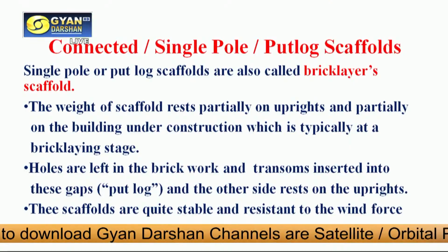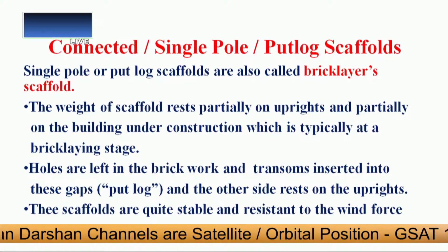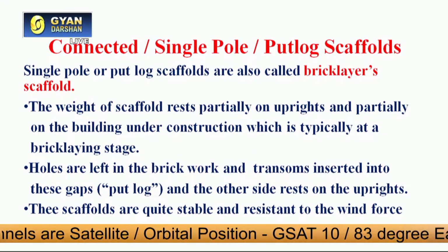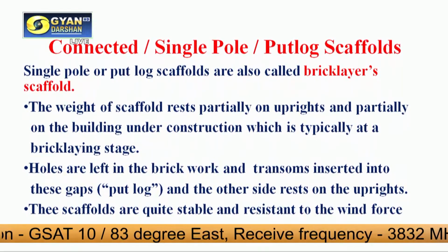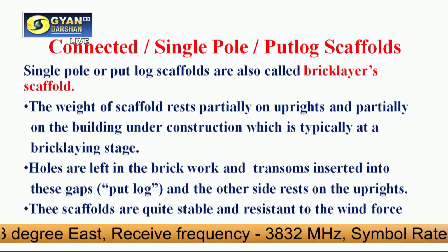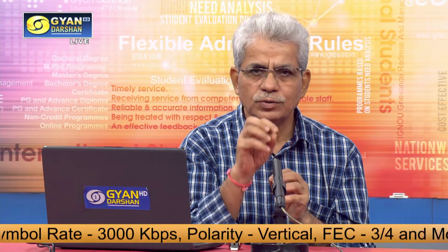The weight of this scaffold rests partially on the uprights and partially on the building under construction, which is typically at a bricklaying stage. As I told you, during the construction we are leaving some openings or holes in the wall, and in these holes the horizontal members, the putlogs, go in and provide support, and the other end is secured to the ledgers. So that way these putlogs are helping in the load transfer mechanism in this type of scaffold.